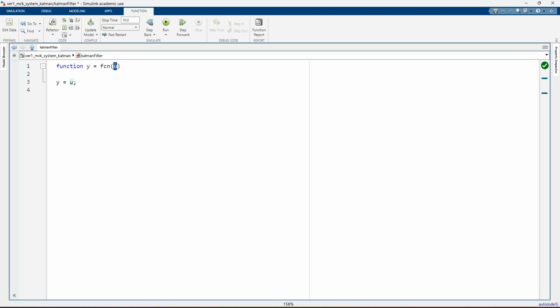First of all, the measurement y should be taken in here, f should be taken, the y filter init value should be taken because the previous and the present state should be used in here, and also the p init value, with which we update the prediction rate or the covariance of the error signals in here.